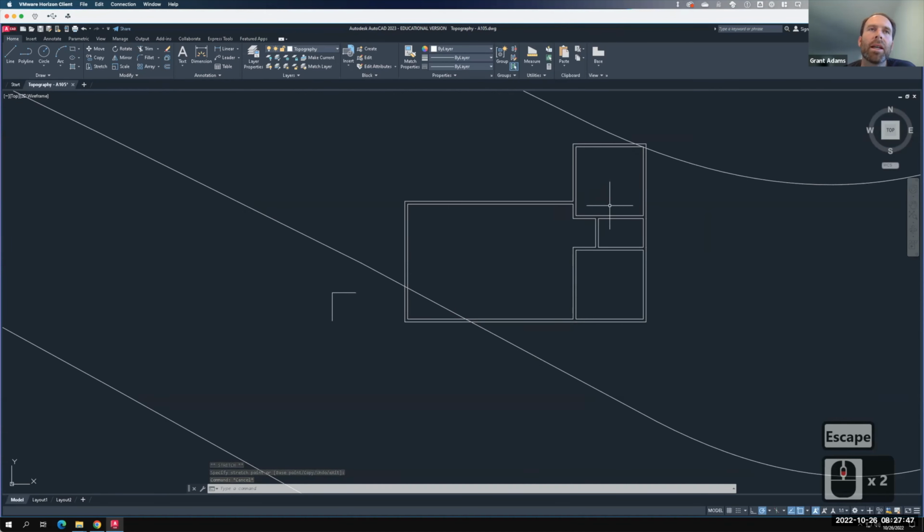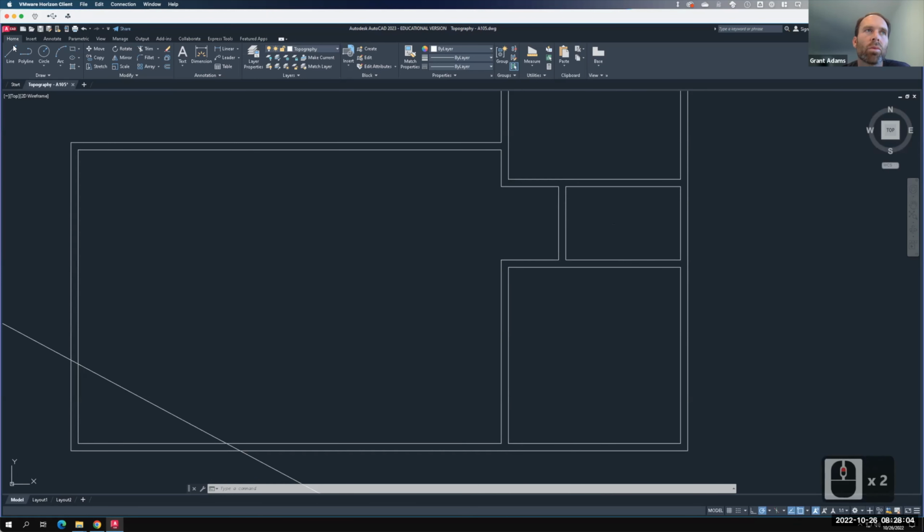Now, just like we did in our last class, we do need to add doors, windows, and that sort of thing. What we're concentrating on today is actually starting to develop a floor plan. What does this look like? So I have 2 bedrooms here. I have a bathroom here. Obviously, I need doors into those 2 rooms. So maybe I'm going to come in here. Let's go at 4 inches away from this wall. And we'll drop that in.